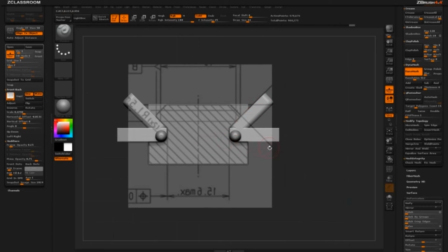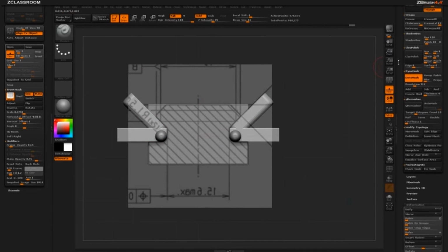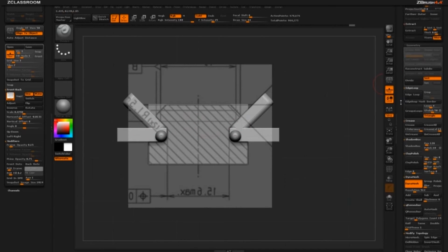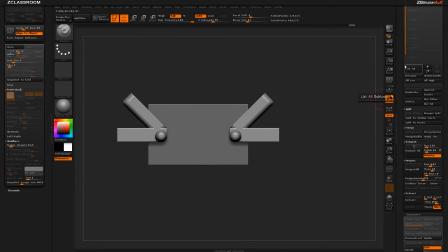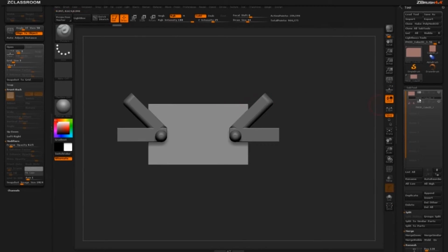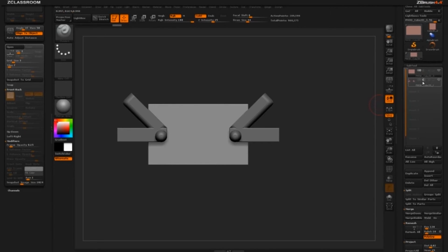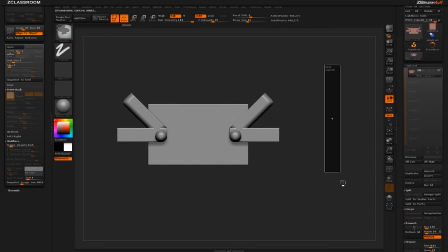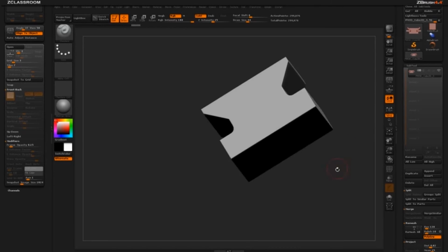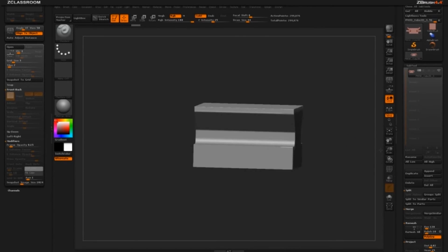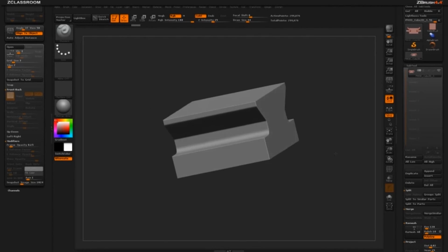With the clip brushes, I could clip one side, but it's not going to clip on the other side, so you'd have to make one clip and then try to match the second clip on the other side. So with DynaMesh Sub now, you can just mirror your geometry as much as you want, and then do the subtraction process. So we're going to do the subtraction now for this. I just have my cube selected, turn on the subtract option on the second subtool, do a merge down, hit OK, and then re-DynaMesh. And so now you can see the rail is starting to take shape. So we've got those carved elements subtracted out of it now.